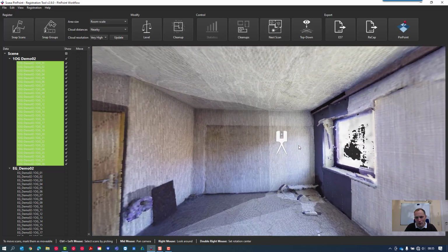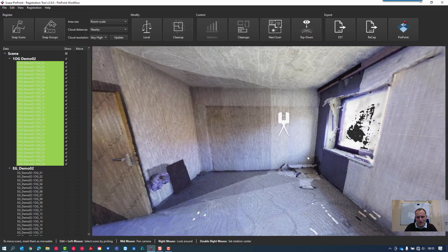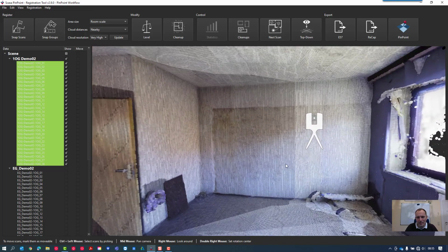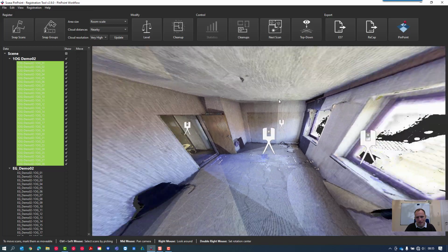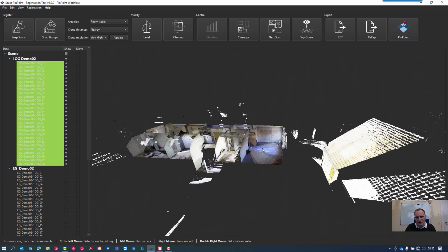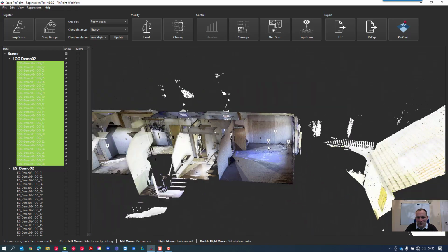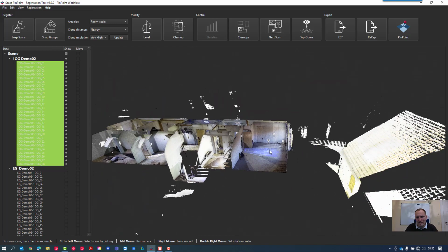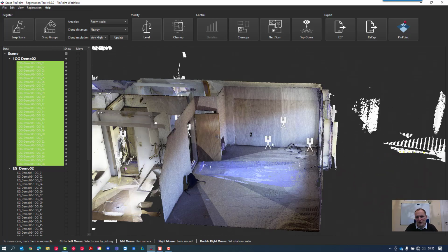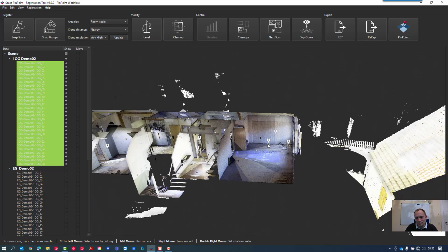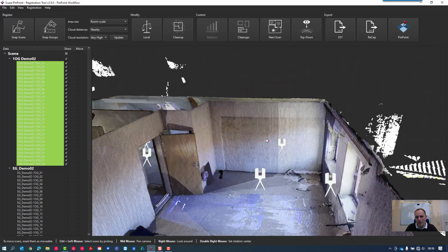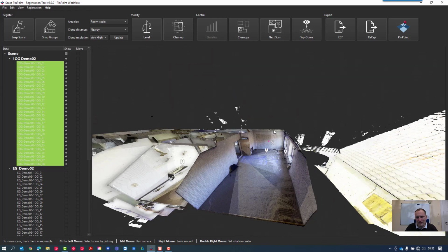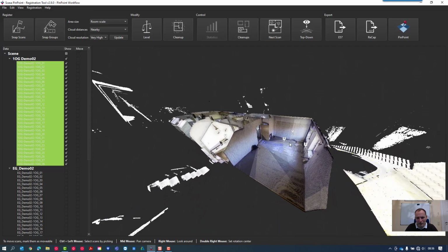Next point we need to talk about is the zoom function. You can zoom in and out using your mouse wheel, but you will see there's a limitation. The limitation is set by defining the rotation point, to make it more comfortable to navigate. So if you'd like to zoom out or in all the way, use the following options. Hold down your shift key and then move your mouse forward and backward while clicking the right mouse button. And then you can zoom all the way in or all the way out, depending again on your need.